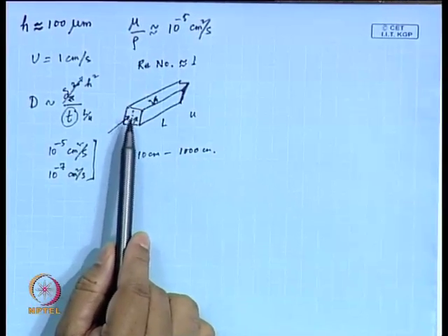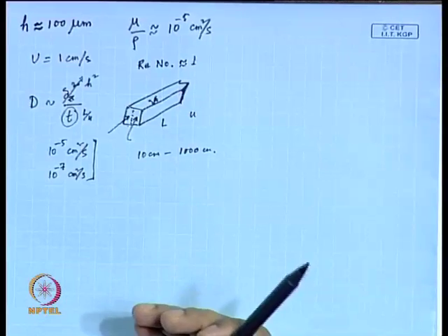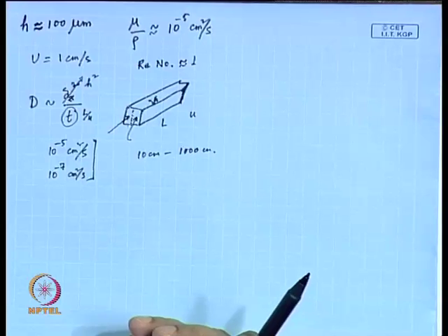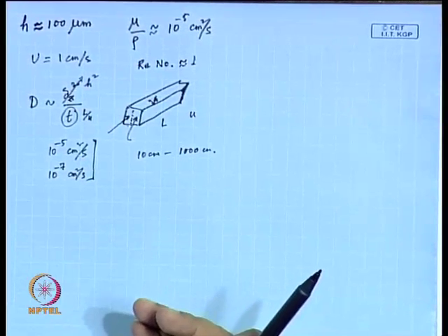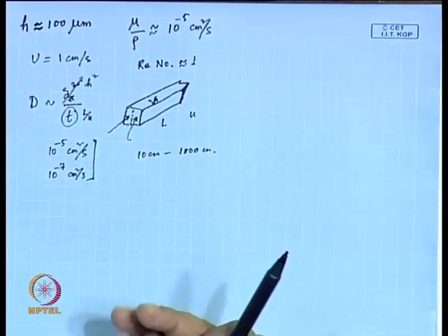So, you have to have some other mechanism by which you increase the interfacial area. That means, the two streams are flowing side by side. If you introduce so-called, in layman's terms, baffles, by which you introduce extra interfacial area over which the mass exchange can take place, then probably you do not need such a long channel.